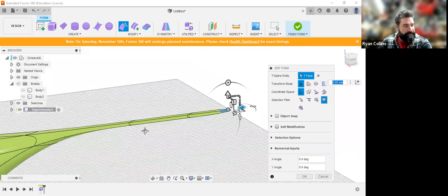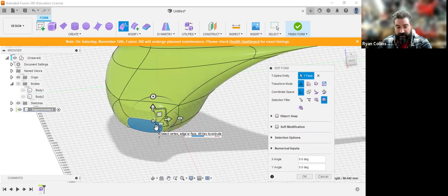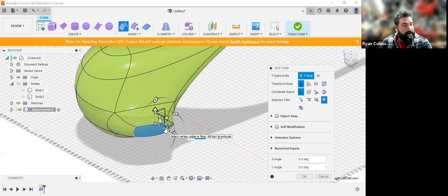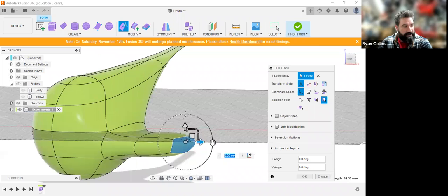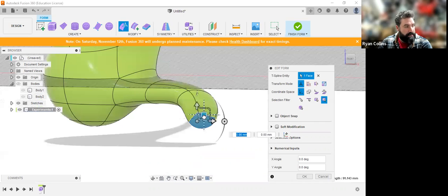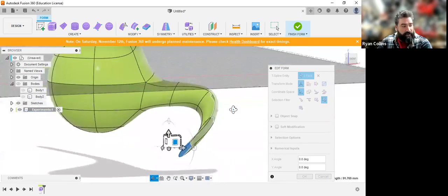Now, if it's round, and you want to create an extrusion there, press and hold Alt again. Or what you could do is press and hold Alt Control, or again, if you're on Mac, Command Control, and it will create a crease, a sharp bend. Press both. You see instead, much sharper. This is very useful if I'm actually rotating something like that. So you can just really start pulling things out and such. So this is how you can really play around with these shapes.